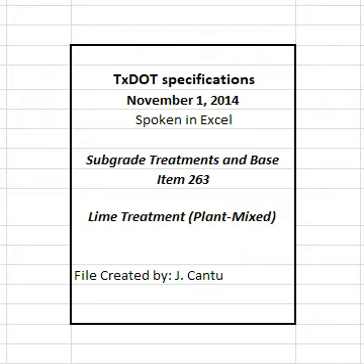4.3 Compaction. Compact the mixture using density control immediately after placing unless otherwise shown on the plans. Multiple lifts are permitted when shown on the plans or approved. Bring each layer to the moisture content directed. Sprinkle the treated material when necessary in accordance with Item 204, sprinkling.